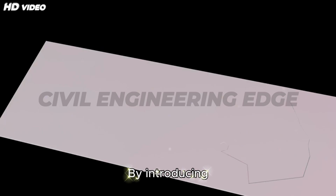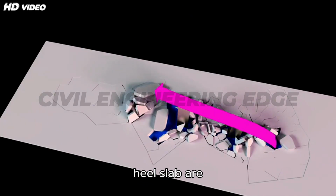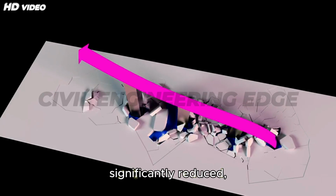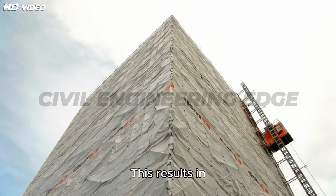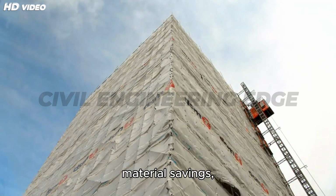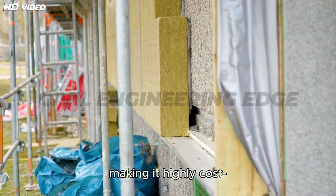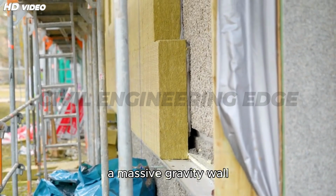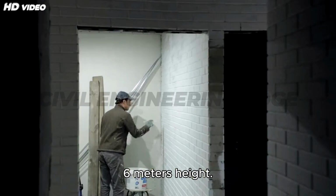By introducing counterforts, bending moments in the stem and heel slab are significantly reduced, enabling the use of thinner sections and less reinforcement. This results in material savings, especially in large-scale or tall walls, making it highly cost-effective compared to a massive gravity wall or even a plain cantilever wall beyond 6 meters height.